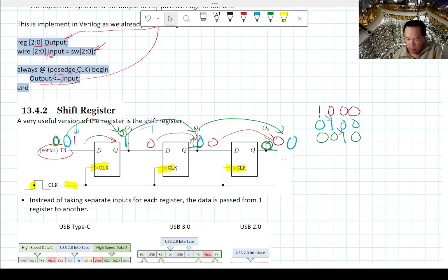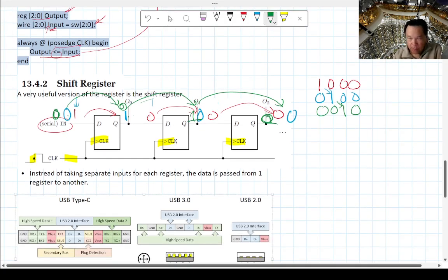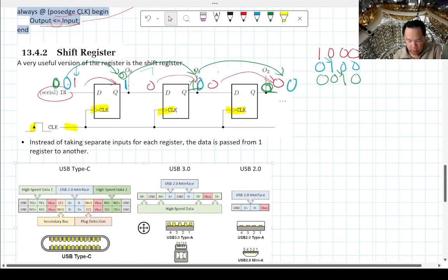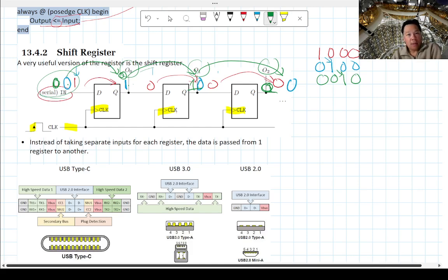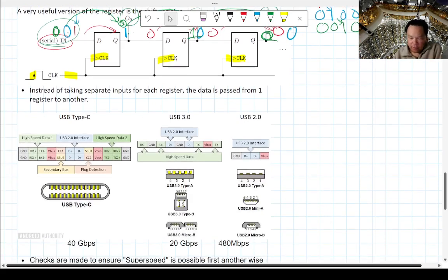Okay. Those of you who know programming, this is known as a bit shift also. So this is a shift register. So why is this useful? You have a list of data that's coming in, and it's being placed in certain bits of your register depending on how many clock cycles it went in. So hopefully the name serial might have given the name of the technology away anyway.